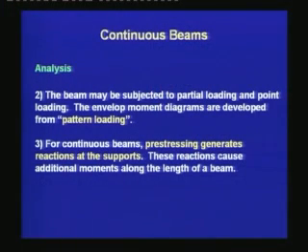The second aspect in the analysis of a continuous beam is that the beam may be subjected to partial loading and point loading. The envelope moment diagrams are developed from pattern loading. For a simply supported beam, a live load for a certain length of the span does not give the critical condition. The critical condition is when live load is throughout the length of the span.